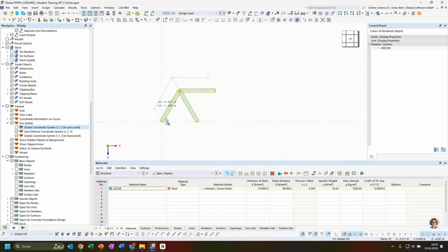going somewhere in my working window can copy this substructure, and I can also snap to the existing node or some grid points to place this substructure another time at this location. And I want to connect it with the first one, so I could just do it like this, and I would have 3 additional members very quickly.